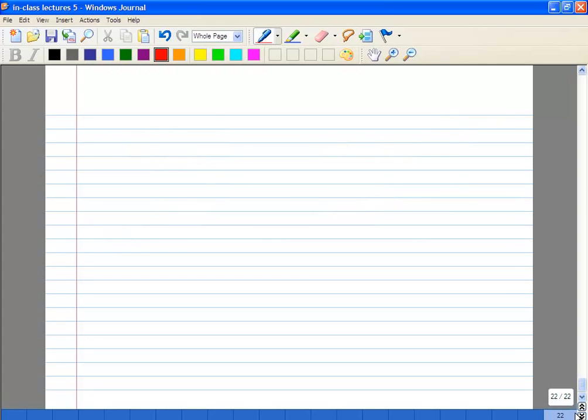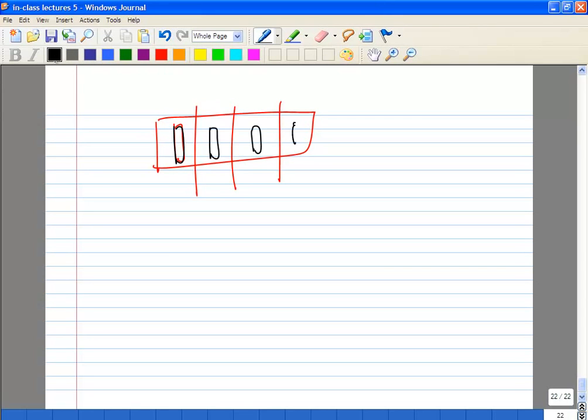What else? You can fill. Obviously, we looked at filling on the bias circuits. The other thing to know for transistors, don't stack up too many metal lines on the drain and source, because you'll have extra capacitance to the gates. Fill up just enough so that you meet current density requirements.